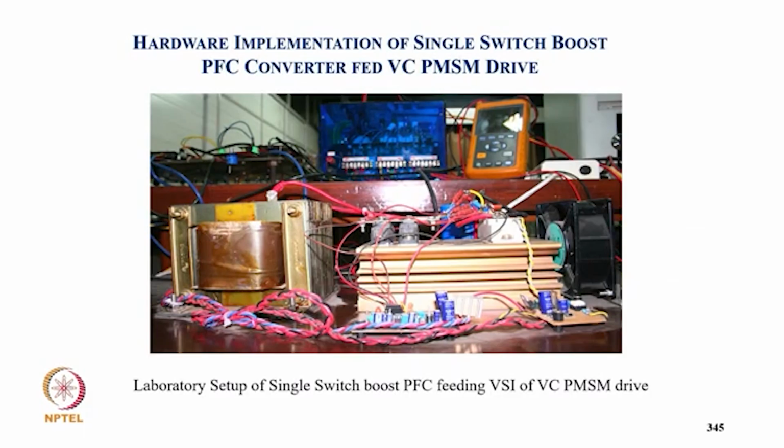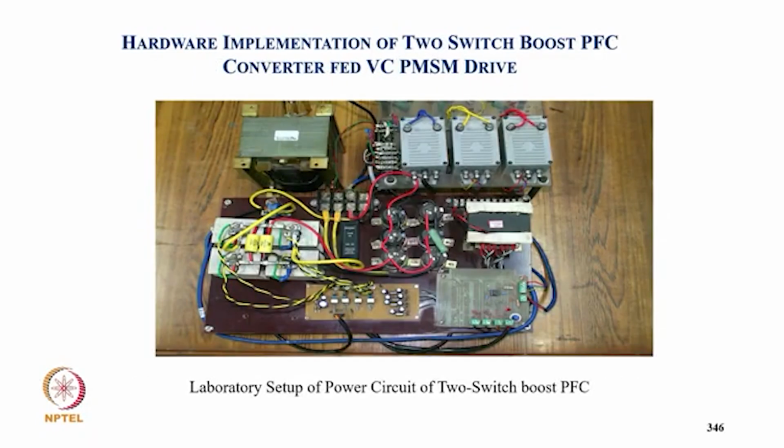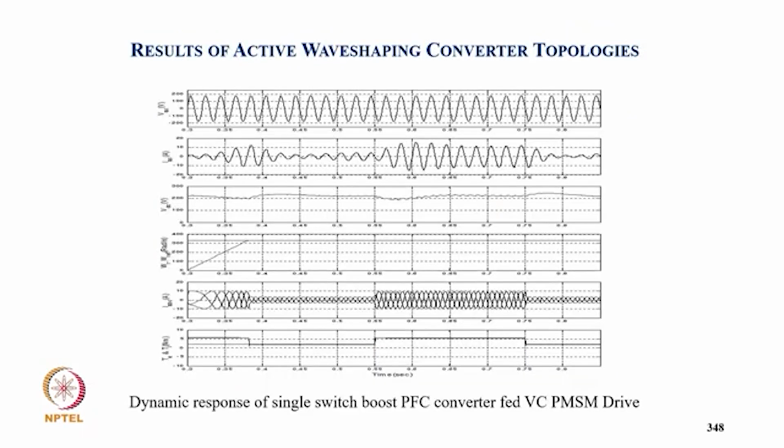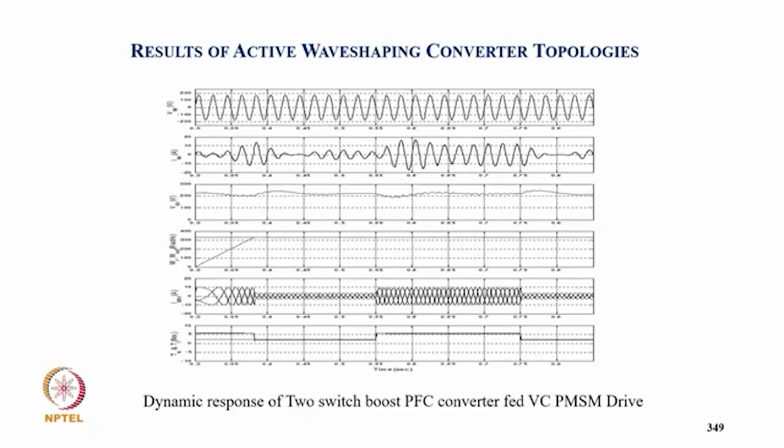And this is typically the hardware implementation of a single switch PFC converter fed vector control induction motor drive. And this is the laboratory power circuit of the two switch boost converter, and the laboratory setup of the control circuit of the two switch boost converter, and these are the simulated digital dynamic responses with the single switch boost converter. So you can see the supply current during starting, then load application and removal, with the supply current in phase with the supply voltage and remaining sinusoidal. This is the case for the two switch boost converter.